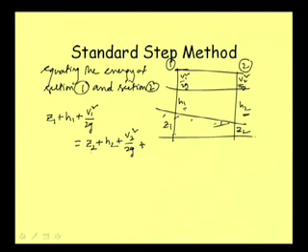In this part we are adding two types of loss. One loss is due to friction, that is, hf from the friction slope itself, we can directly get this hf. If the distance delta x is very small, then we can get it as the friction slope SF multiplied by delta x. But apart from that friction loss, there are some other types of loss also.